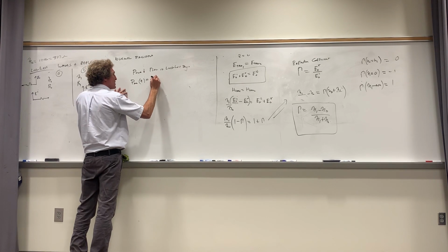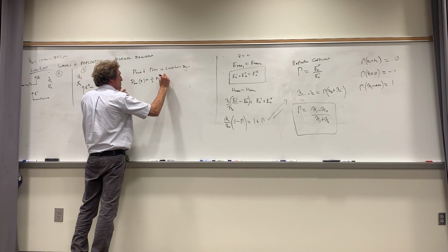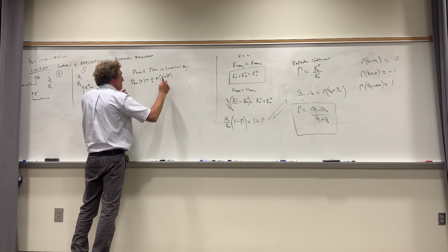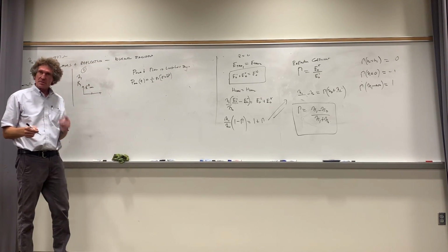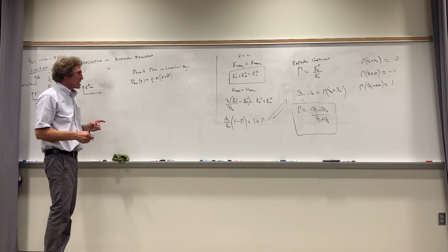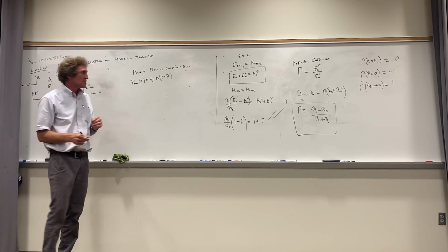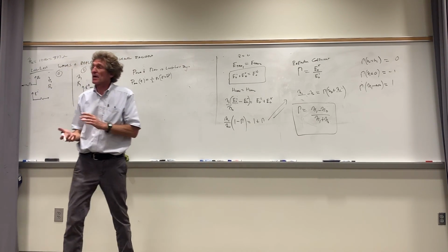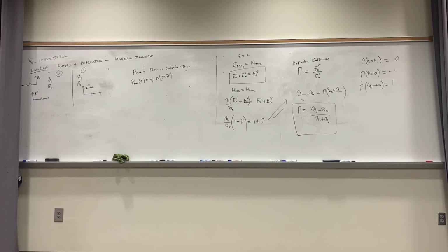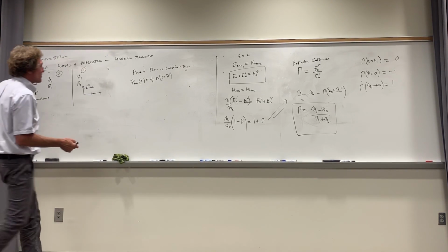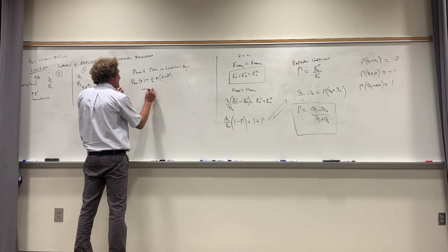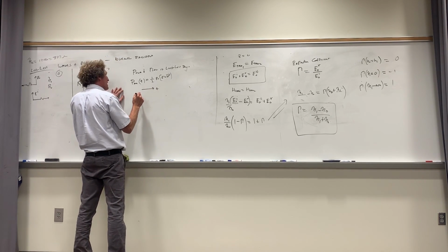That's 1/2 the real part of E cross H conjugated, right? Now just listen to me. Y'all realize that H is equal to the E field divided by eta, right? And there is no alpha. Let me do this for you. I'm going to do this power flow just for the positive traveling field in region 0.